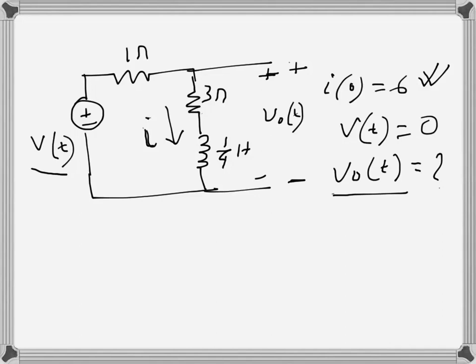So we have to look at the current. The current is an inductive current, so inductance will not let the current become 0 instantly. It will try to hold the current. So the current will be an exponential decay current. It will be the transient current, and of course the voltage will also be transient. So let's look at the current here. There won't be any steady state current because there is no source afterwards. This current will pass this way and then it will decay to 0.